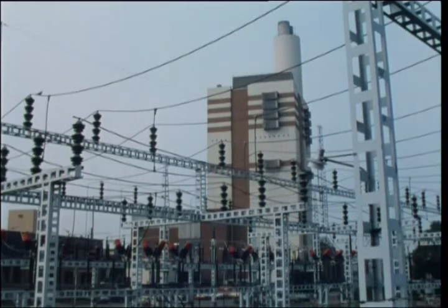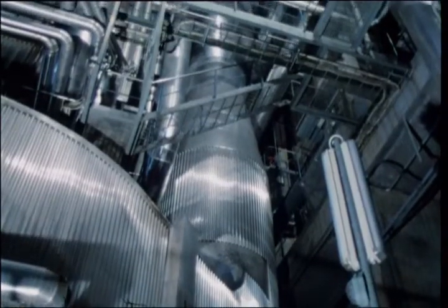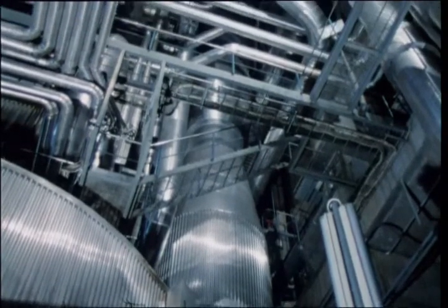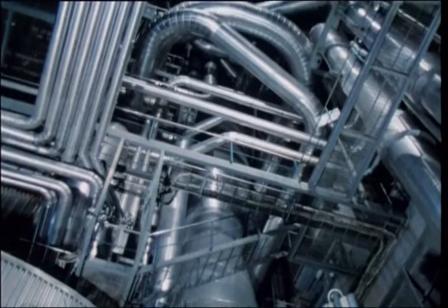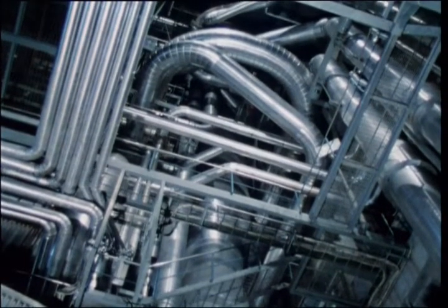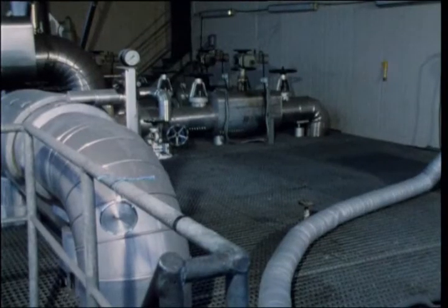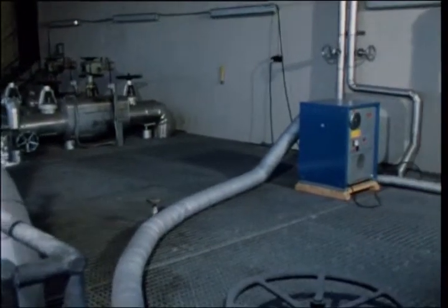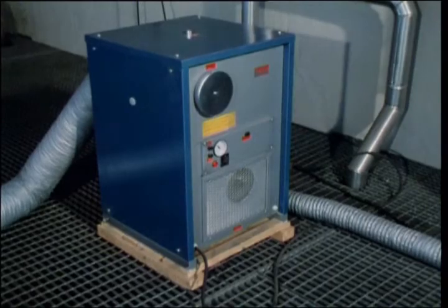A larger application of dry air was to protect a generating station while out of service. It was to be shut down for a 5-year period, with the ability to restart within 3 months. Incoming air was dried by machines located around the building to keep important components at a relative humidity of about 50%.